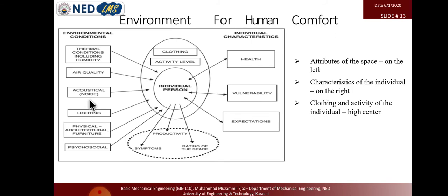In industry there will be noise of machines, so where I was working, in General Tire, in Ghandhara Industries Limited, we had a meter that measures the acoustic level, and we do not allow an operator to work with an acoustic value of more than 80 decibels, because it damages their ear system forever.